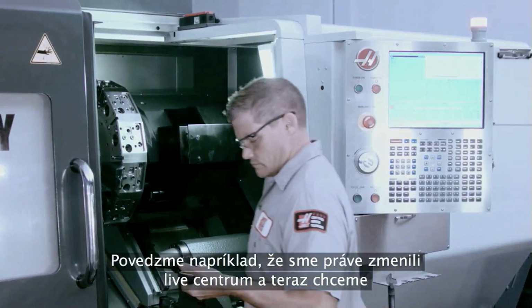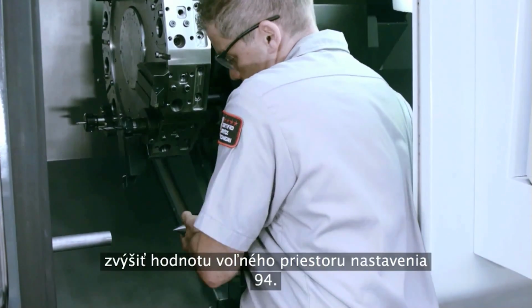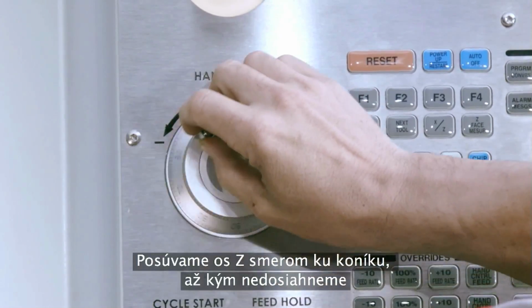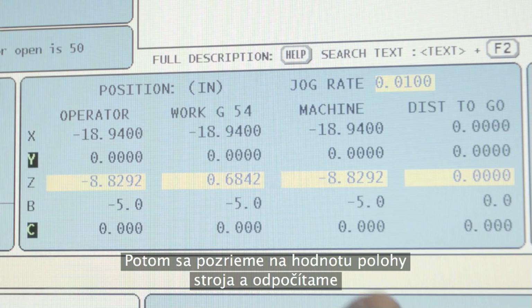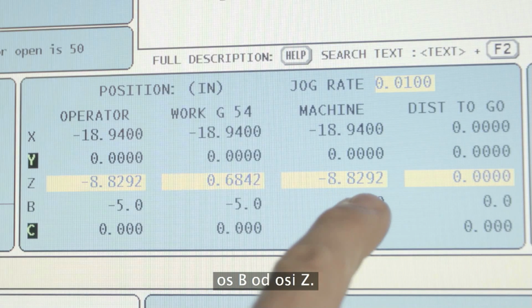Let's just say, for example, we just changed to a different live center, and now we want to increase our setting 94 clearance value. This is how we would do it. You jog the z-axis towards the tailstock until you reach what looks like enough clearance. Then we look at the machine position values and subtract the b-axis from the z-axis.